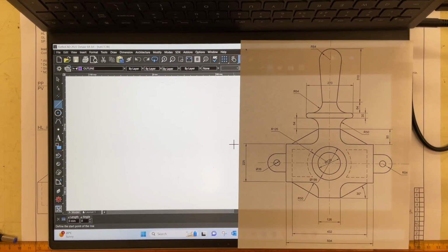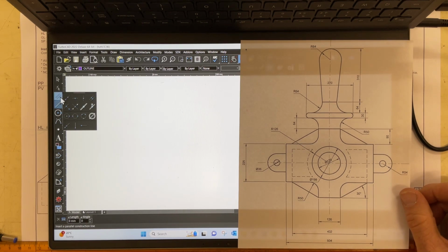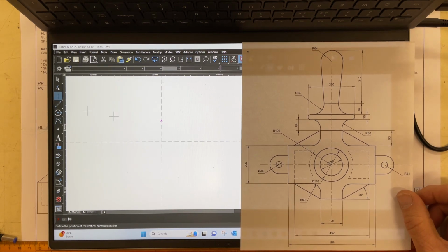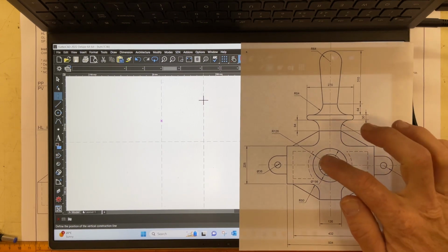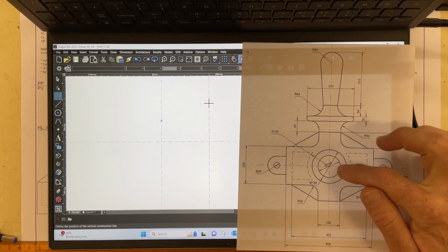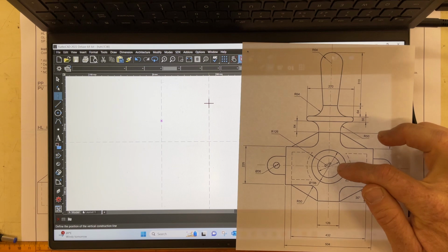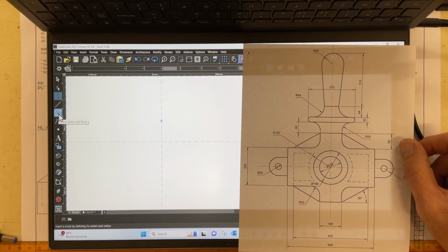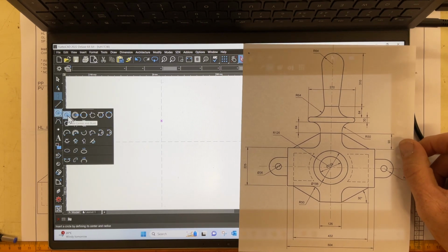Right, here we go. This is the next little exercise that we need to draw. I'm going to come in here, do a nice long click on there, get a horizontal construction line, put in a vertical construction line, and let's always start from drawing out from the center, and the first thing that I can see is a diameter circle of 129, and the next diameter says 198. Now those are really big dimensions. So let's go in here, let's pop in.